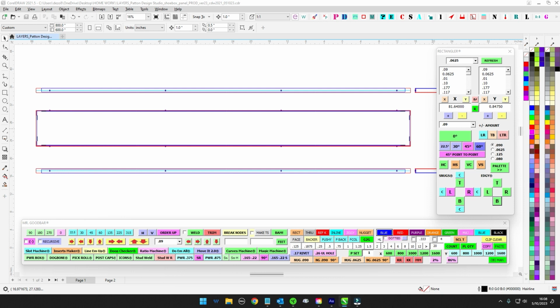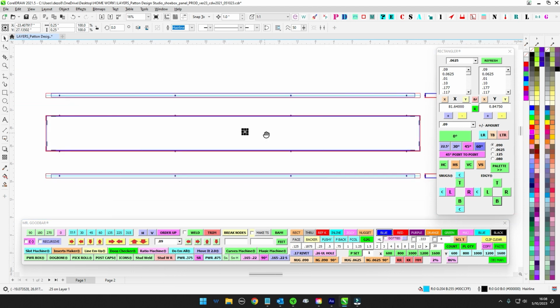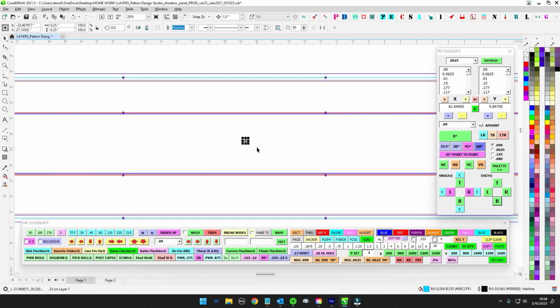So what I like to do is pretty much have a minimum of a 1/4 inch hole when it comes to installing this stuff. Because at minimum, if they're going to be putting this on drywall-covered studs in an interior, they're basically going to be using number 10 stuff. Like if they're going to be using a toggle bolt, it's going to be a 3/16 toggle bolt, a number 10.